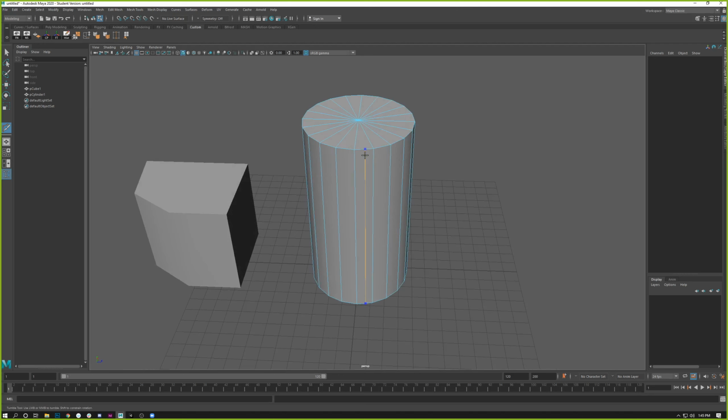And for those that see what's happening here, it's not going any farther because remember that these are tris. You can't cut across the tris, the exact same way the selection tool works. But if I do a couple cuts in here first, you can see it will indeed go across those because they're quads. It just stops at the tris.